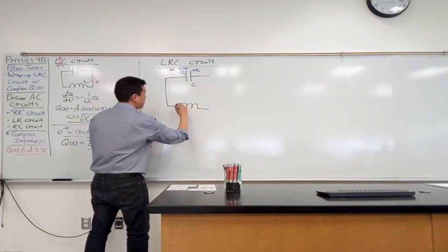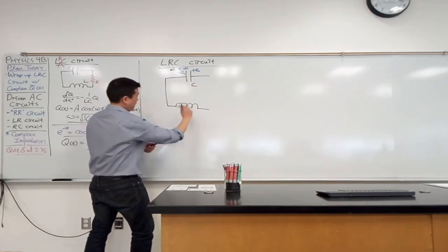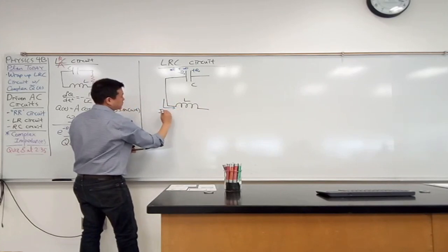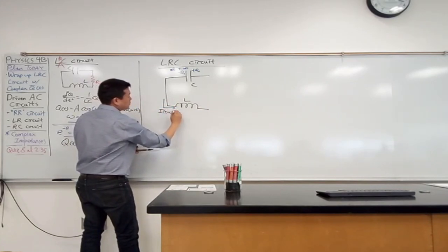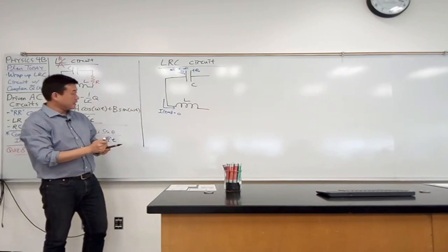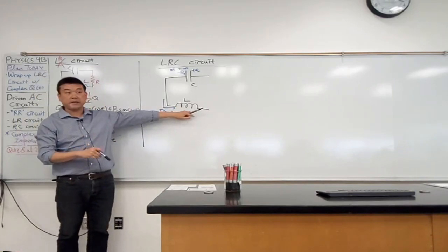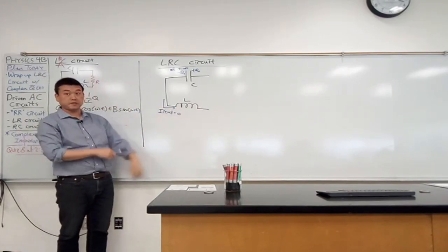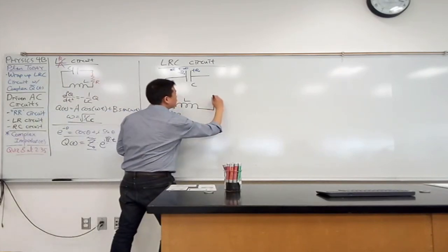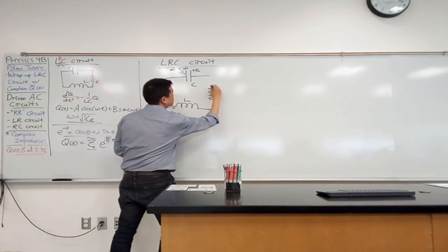And we will say that the way we have this set up, the amount of current that flows at time equals 0 is 0. So we close the switch at time equals 0, and the inductor forces current not to change so suddenly. It has to change at a finite rate. And the new part that we are going to introduce now is the resistor.